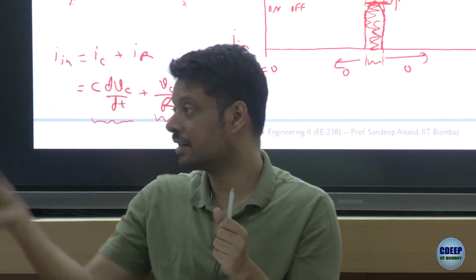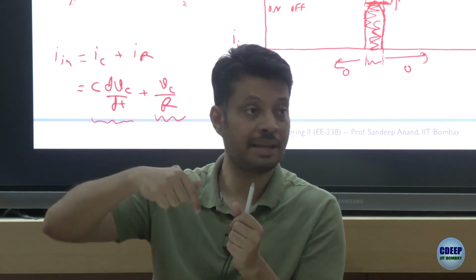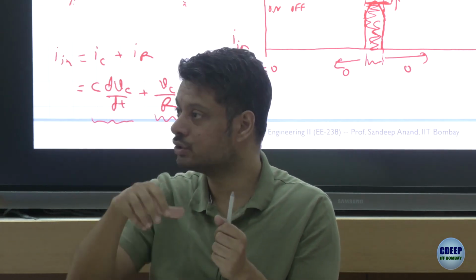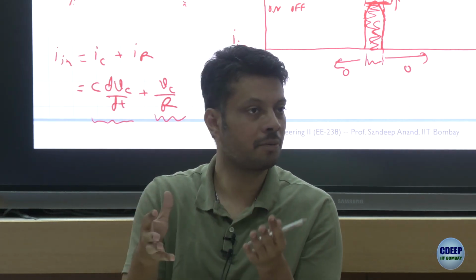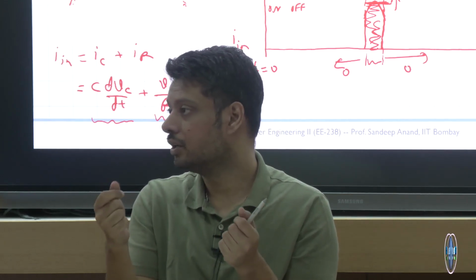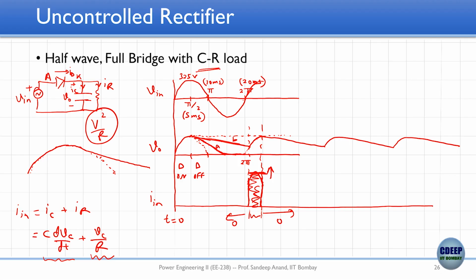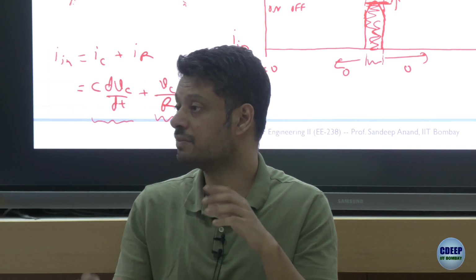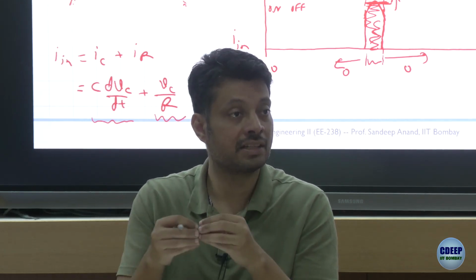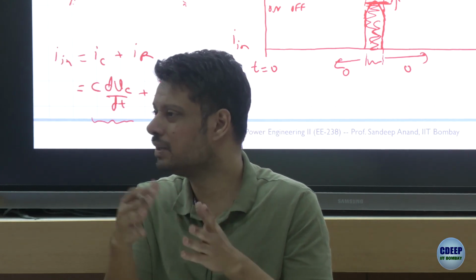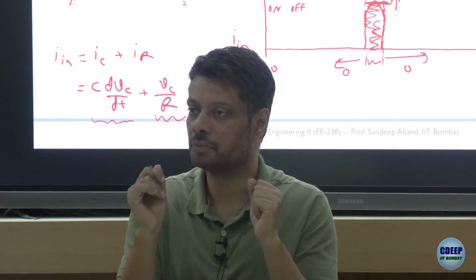What will happen is it will create a voltage drop in that wire which is also of the same nature. So the voltage that you are getting in this room will start distorting, and you would not prefer to have that kind of voltage in this room, right. So rather than the constraint on diode getting damaged, it's more of something we call power quality, and we'll talk more about it in the later half of the course, where power quality defines the quality of the voltage and the quality of the power that we are receiving, right. So if the C is large enough, the power quality may deteriorate, or rather the voltage quality may deteriorate, but that's something which we'll dig upon later. Let's not get into it now.